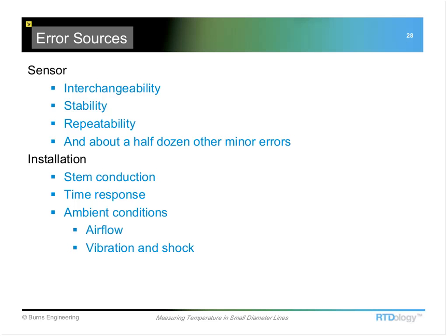After a little question and answer with the end user, we found out that a fan had been turned on and was blowing on the location where the sensor was installed, and that was enough to cause a 0.5 degree C error in that measurement.